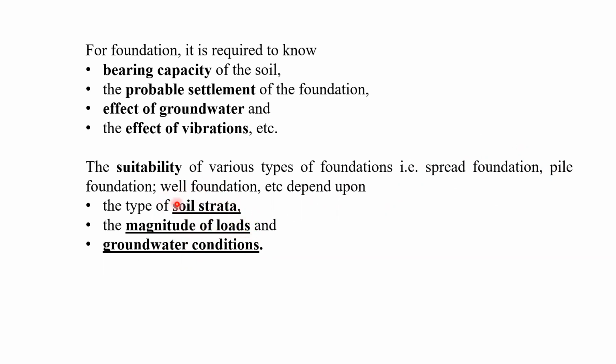So depending upon the soil strata, suppose a soft soil strata is there below the ground level. In that case, we have to think which type of foundation will be suitable. If these three conditions are there, we have to also consider the magnitude of loads of the structure, what type of strata are available below the ground surface, because some soil strata may be weak, some may be strong.